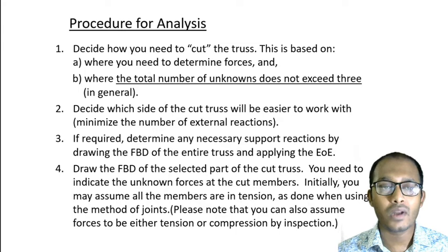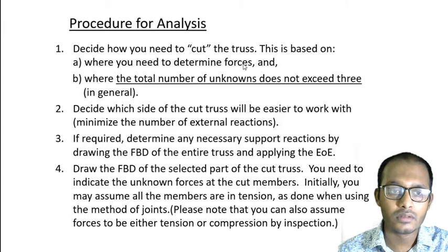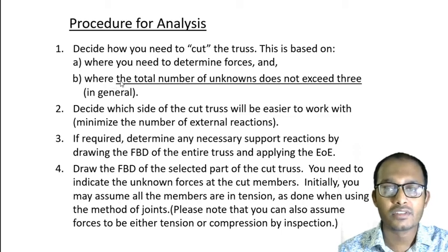So now what is the procedure of analysis for this kind of truss? Okay, so at first you need to decide where you will cut the truss. Decide how you need to cut the truss. This is based on two criteria: number one, where you need to determine the forces, that means the unknown forces that are asked of you to determine, and number two, the total number of unknowns does not exceed 3, that I just explained.